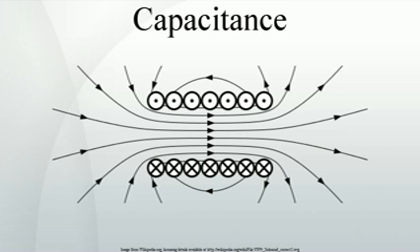Measurement without the dielectric in principle means measurement in free space, an unattainable goal inasmuch as even the quantum vacuum is predicted to exhibit non-ideal behavior, such as dichroism. For practical purposes, when measurement errors are taken into account, often a measurement in terrestrial vacuum, or simply a calculation of C0, is sufficiently accurate.